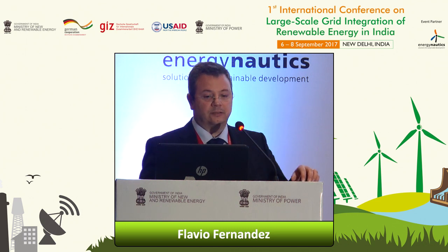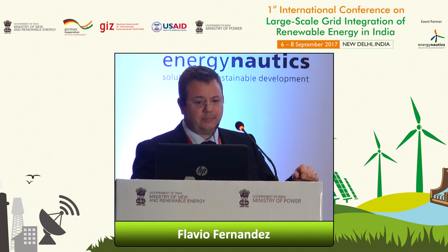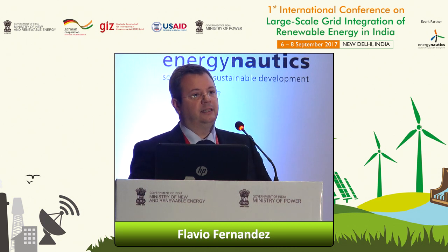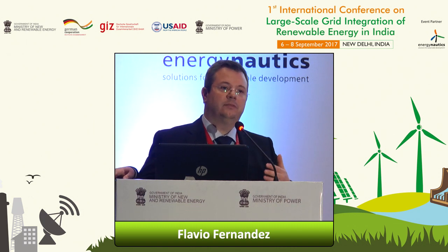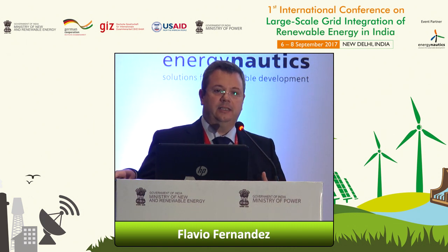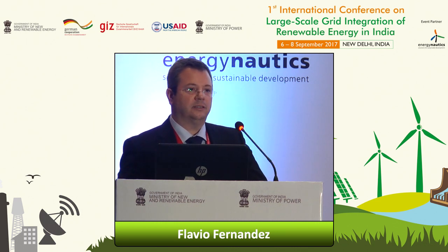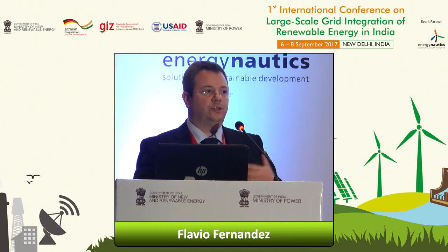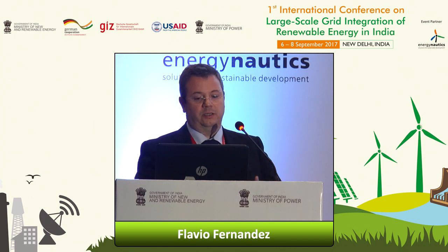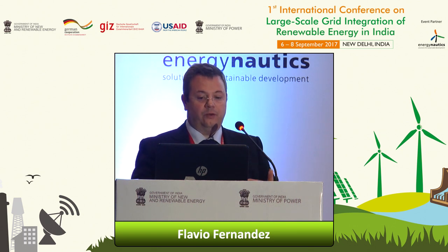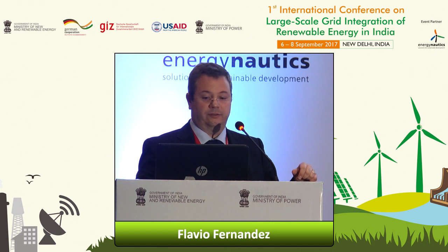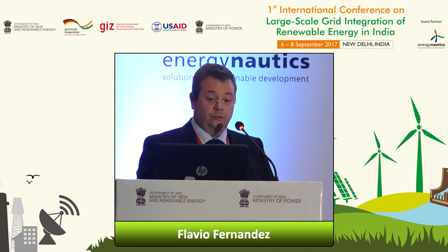And I would like to point your attention to the IEC standard. This is a way to overcome the portability issue across different platforms. The IEC standard defines that, no matter where you develop the model, you can compile it according to some rules given in this standard, so that you can take the model into another solver. By the time you initialize the model, you can parameterize it, get access to the equations for the initialization, and also run the simulation. So basically you solve the differential equations there. This is a good solution also.